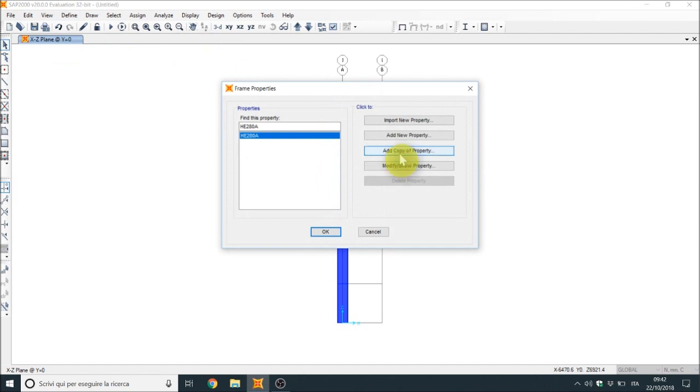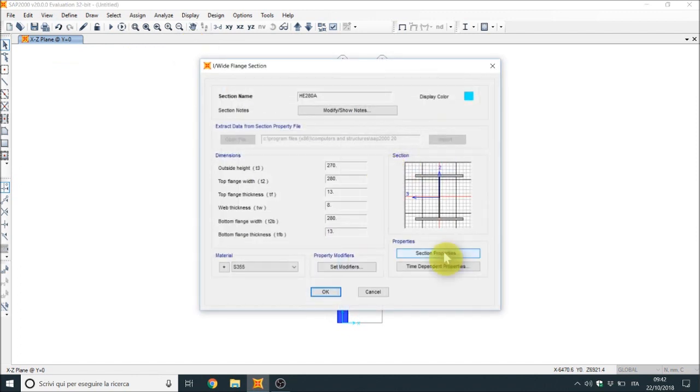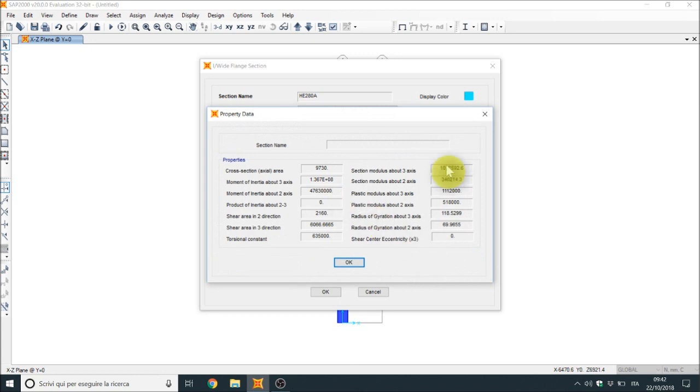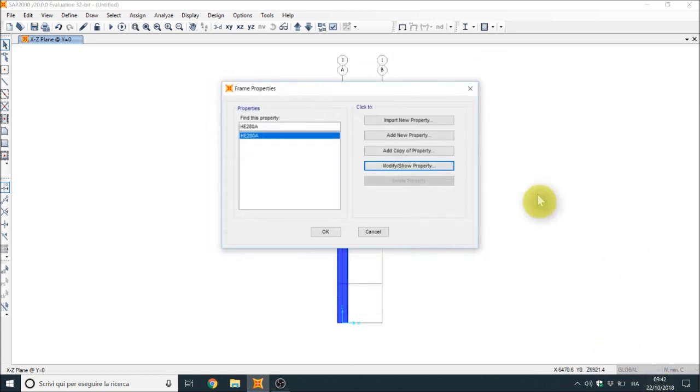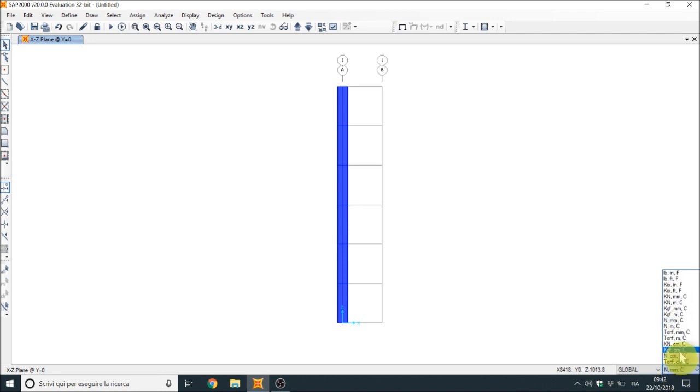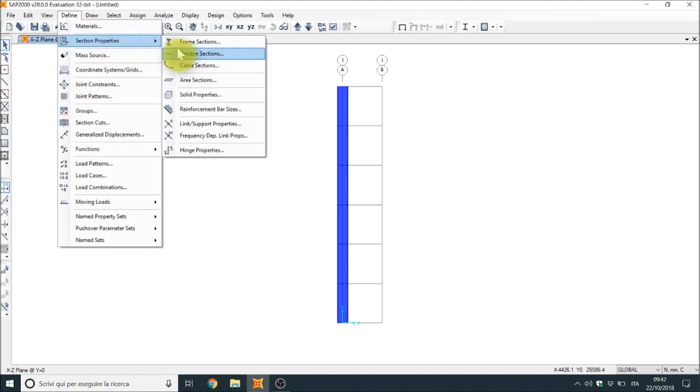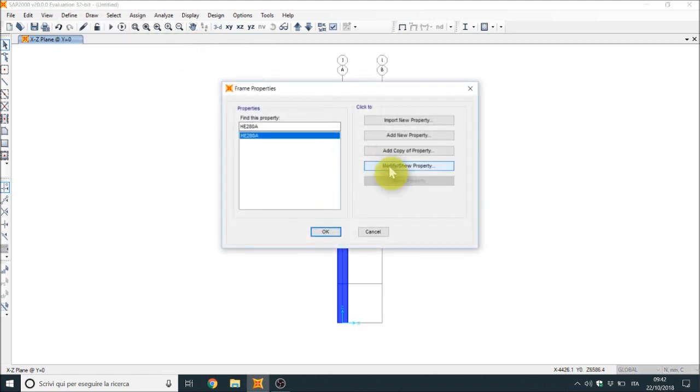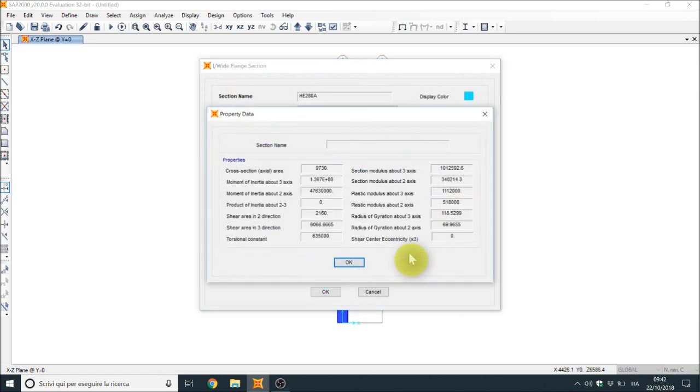We can calculate, for example, first of all, the buckling, starting from the inertia. This is the in-plane buckling, which will be a double supported beam. We have a double symmetrical cross section, so the buckling will be flexural buckling.